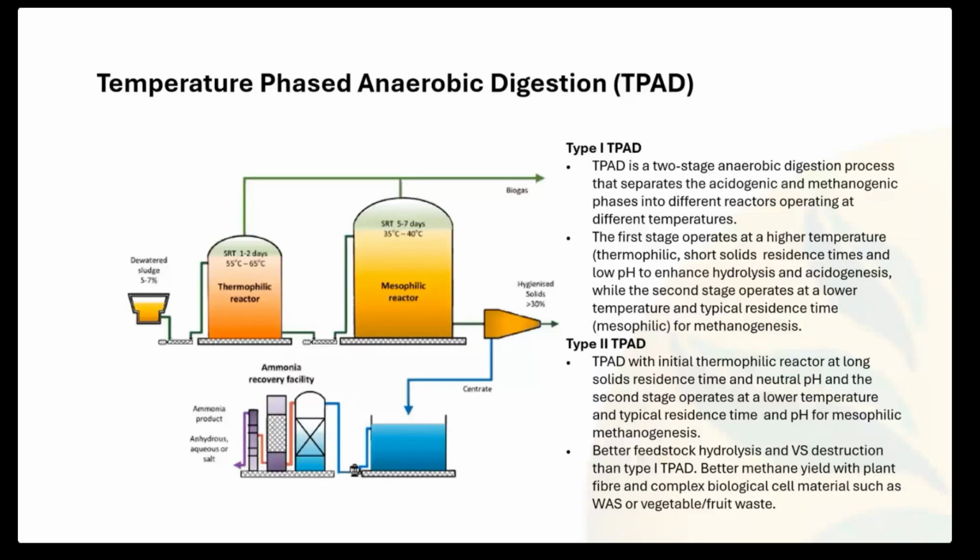And the acid is then pumped into a methane reactor, and we change this: the hydraulic residence time is preferably 8 to 10 days, not 5 days as it was shown before in the diagram. The solids residence time is typically 10 to 15 days in the mesophilic reactor to degrade the products of thermophilic metabolism.